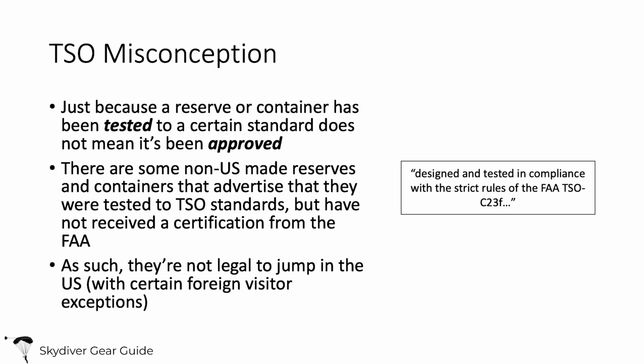For example, from one manufacturer, I copied this from their website, they say that their container was designed and tested in compliance with the strict rules of the FAA TSO C23F. Now that may very well be, but that manufacturer has not applied for a TSO approval, nor have they received one, so it's not legal to jump in the US unless you're a foreign visitor.